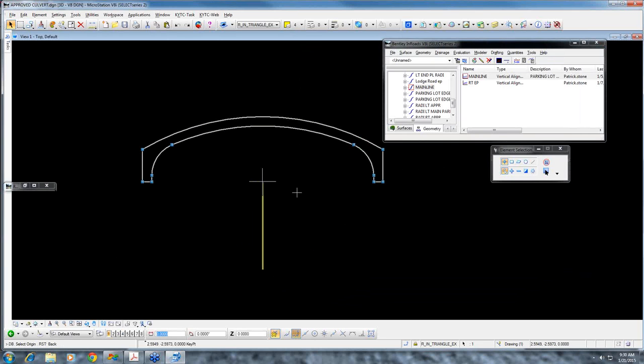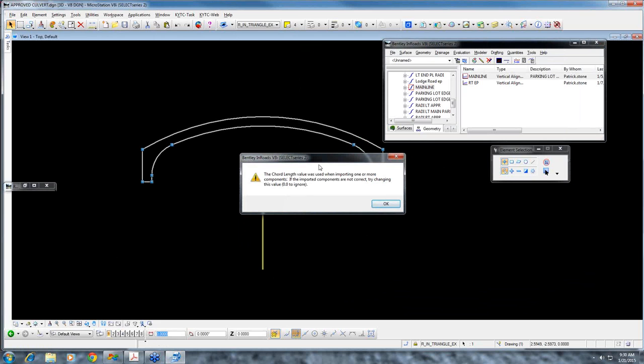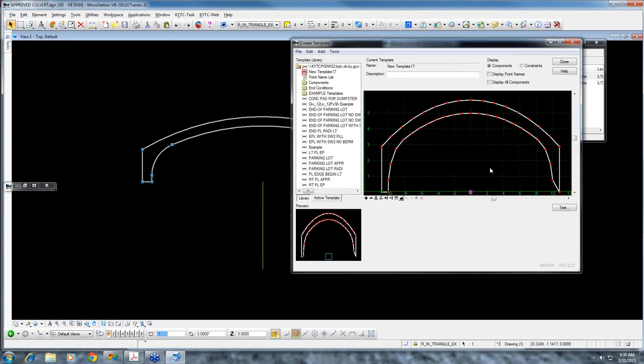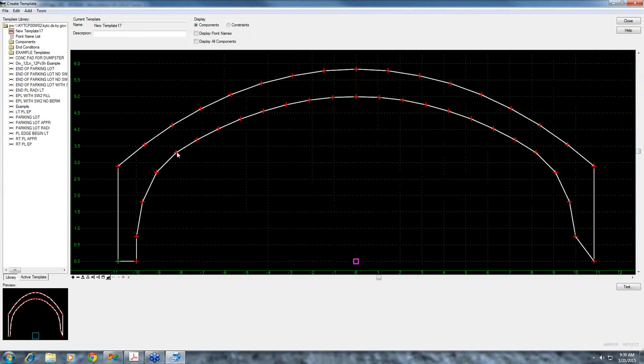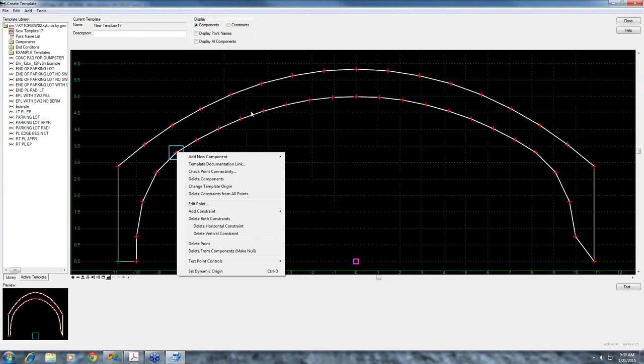So we would need to, there's the origin point. The chord height value, yeah, that's great. I don't worry about that. The chord height is just what it's set on the triangle, and then it's going to chord down through here, and you'll have a bunch of little segments. Okay, and see how it's put all these little chords? That's due to the chord height tolerance and where we've got it set to calculate that.